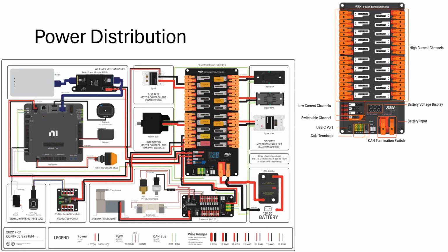So real quickly, this is the big block diagram of how the robot is set up. So you have the battery down here, and it flows through this thermal disconnect, which is our main breaker. So if you pull too much power, if you have too much current, too many amps flowing through here, it will get real hot inside and it will pop open. If that happens, you lose all connection because your battery needs to be a closed circuit. So it needs to go all the way from the positive through all of your stuff and back to the negative. So if this opens, you have no power.